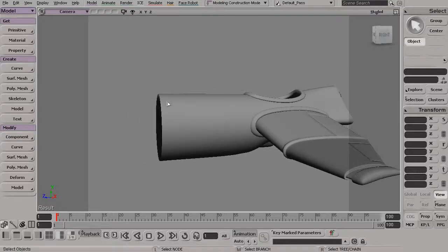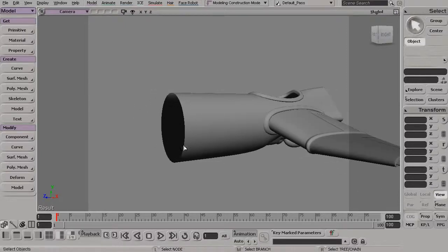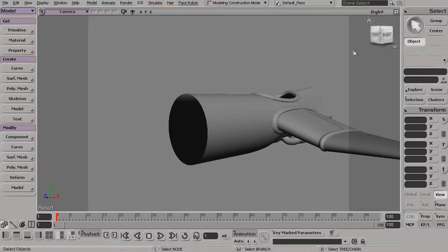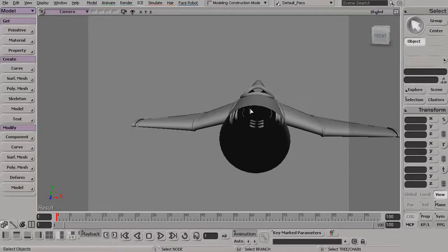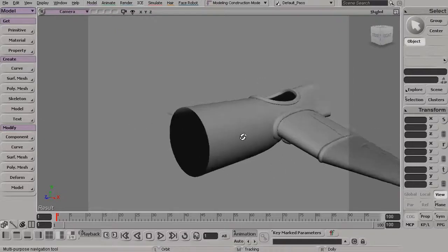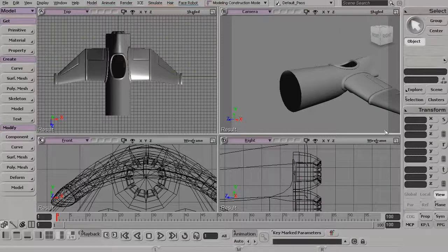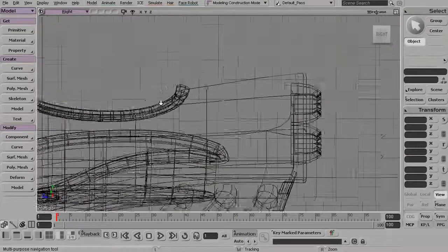So what I'd like to do is create the nose piece here, the part that's going to encompass the turbine blades whenever this is built up. So a revolve is going to work really well, again because this is going to be a rounded surface.